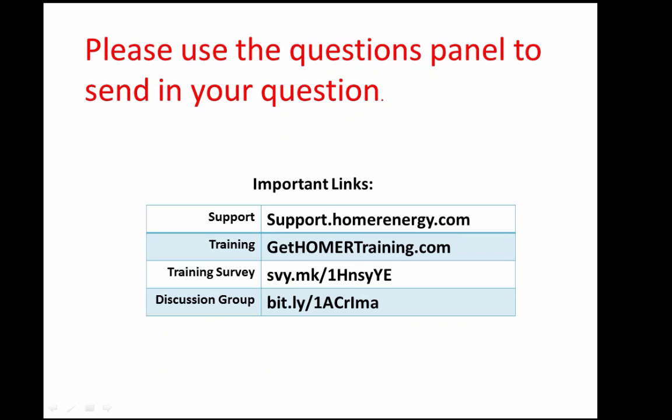We basically included those default loads so that you had a place to get started. If you need one that's specifically tailored to your situation, we also offer a synthesization module that allows you to put in minimal data to generate a realistic load profile for a location. In addition, we allow you to import hour by hour or minute by minute data so that if you have measured data, you can pull that in.